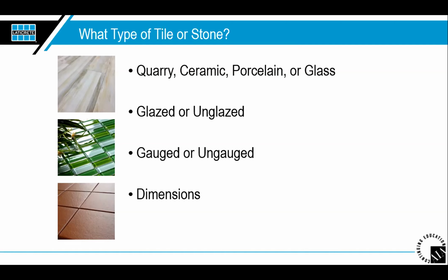So, they had a sloped substrate, but because they're doing a wet set method, they had to continuously keep that slope through the installation, which is going to be a lot easier to achieve when you're talking about a sloped concrete substrate that we can just maybe put a waterproofing down or crack isolation down. And then you could actually keep the slope on a tile that's rectified, and it's a gauged porcelain, so it's all the same thickness, and it's just going to run fluidly with the actual concrete substrate itself. So 2 totally different types of installation there.